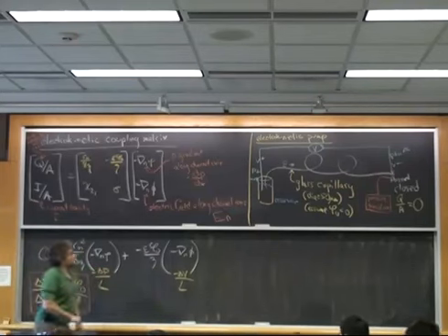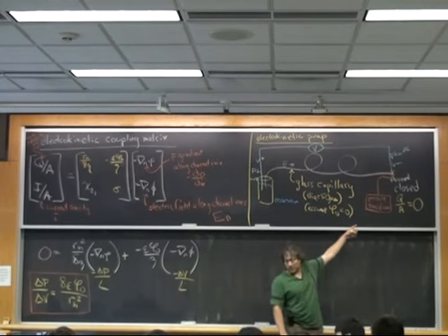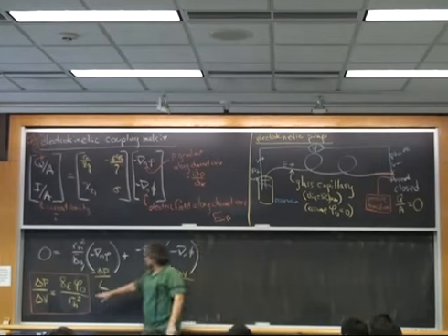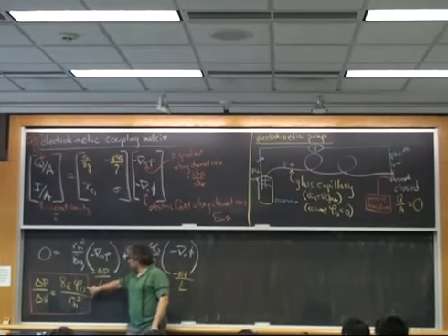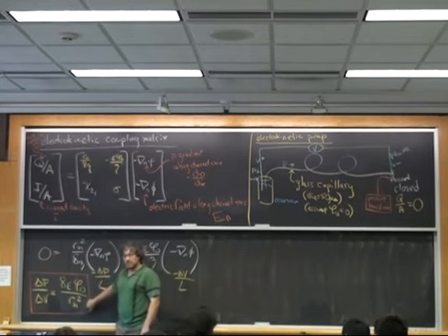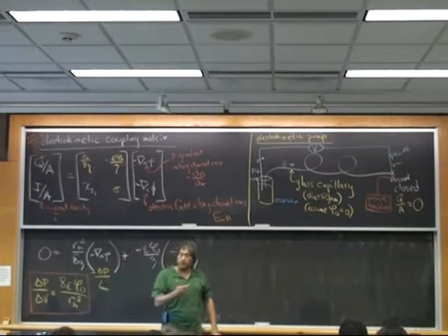So I try to run it the other way. This pressure will go down until the fluid starts cavitating, and then I'll just make bubbles. If I run it forward, I can crank the pressure up. This pressure I generate is proportional to the supplied voltage, permittivity, interfacial potential, and importantly, is inversely proportional to the hydraulic radius squared. And this is the same conclusion we came to at the very beginning when we talked about Couette flow and Poiseuille flow.